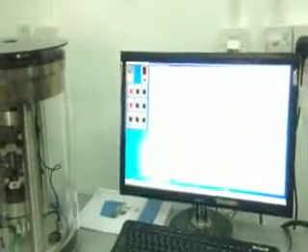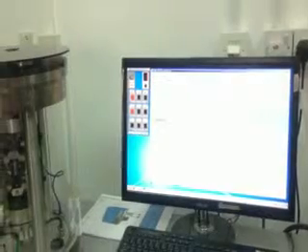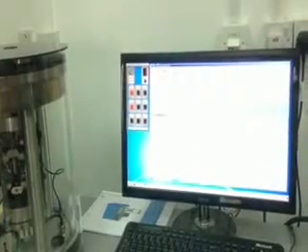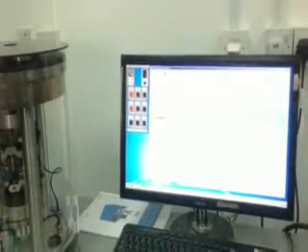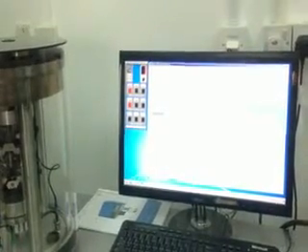So you need to have a feel for what you expect the material to be. The standard gauge length is 70 millimetres for this machine. If you're using, say, UTM 125 or 100 and doing non-standard testing, I think there's one customer using 100 diameter gauge lengths, so you can change the range. But for this machine, they're fixed at 70.